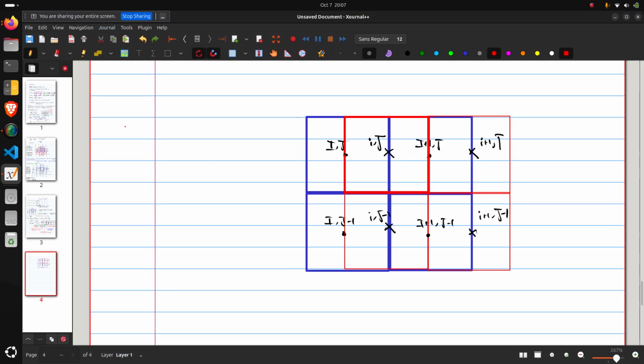So what is the D? F and D were there, no? The diffusion flux was nothing but gamma times delta x, right? And also A is there, so we'll just ignore the A for now for simplicity. So for example, the south face is there. In the south face, what will be the gamma?